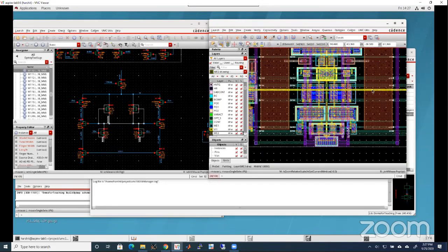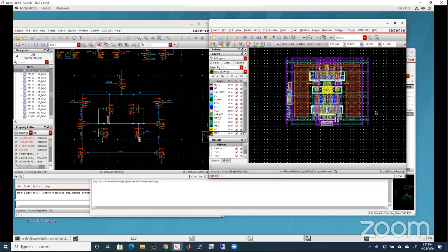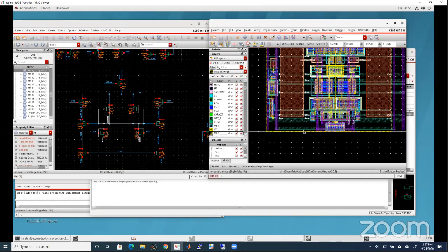So that means these are different metal layers that are connecting in between layers maybe. Yes. And those going horizontally are locally connected? No. Metal 3 is horizontal. Metal 3 is an odd metal layer, so that is why it is going horizontally. We have chosen this convention, and metal 2 and 4 are even metal layers, so they are going vertically.